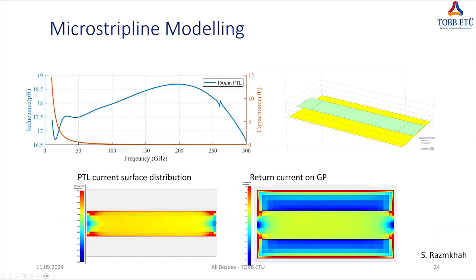Here, for example, the inductance is extracted by using HFSS. But there are also some tools that only extract the inductance, like Inductex. You give the layer definition file of your fabrication process, and then the GDS and circuit model, and then the inductance is extracted. This is similar to the extraction of capacitors in CMOS circuits. In this case, we extract the inductances.